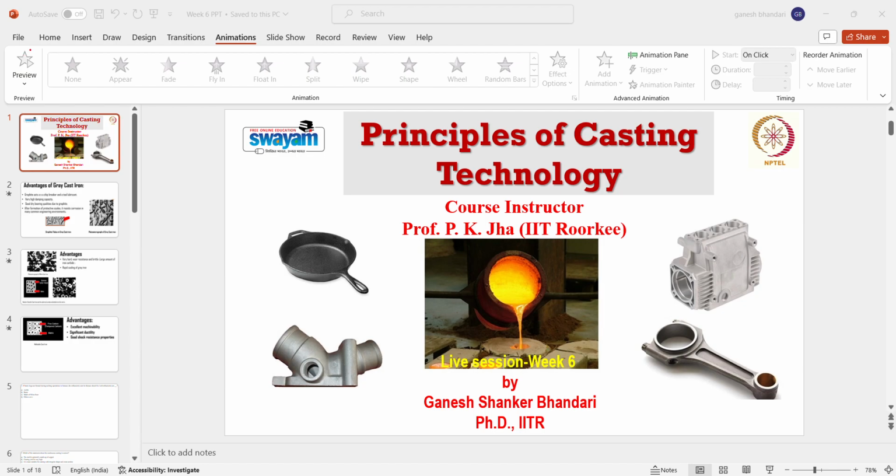Because in cupola furnace we generally use coke, or carbon, as a heating source. So it will be easier to pick up the carbon during melting of gray iron because we are going with the coke. In induction furnace we generally provide the heat with electricity, via induction process. And in open hearth furnace we generally go with oil burning, or if we are heating it with some carbon, then we generally go with the gaseous formation. We form gas from the carbon and provide it in the open hearth furnace as a fuel.